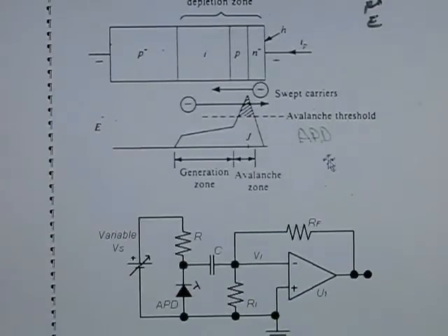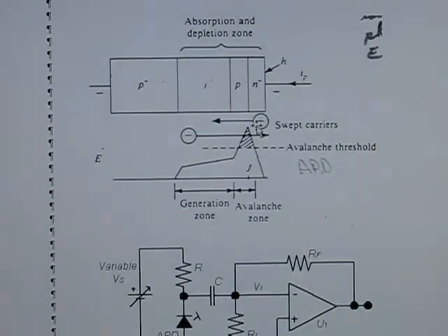So if we take a look at this now with that in mind, what would happen in words is that if an electron hole pair were to be generated, the electron would go speeding toward the positive terminal, and in the process would be passing other electrons and conveying a little bit of energy to them. So they could break free and enter the conduction band, and they in turn would influence other electrons, which would generate other electron hole pairs.